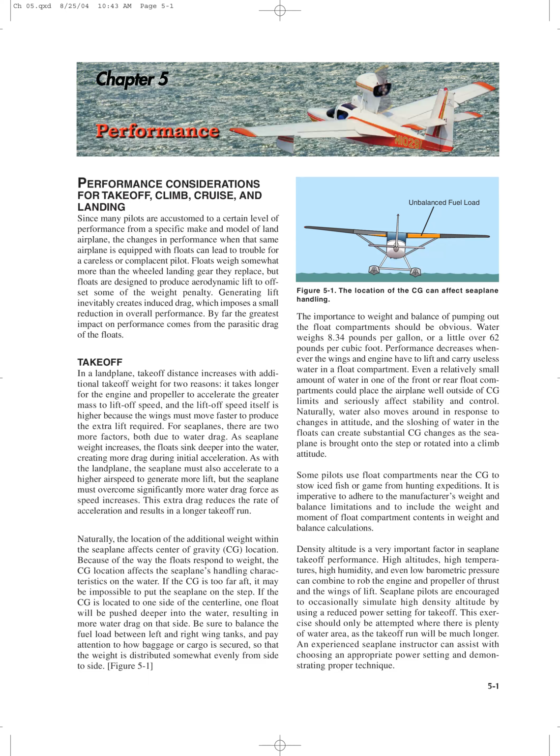Performance considerations for takeoff, climb, cruise, and landing. Since many pilots are accustomed to a certain level of performance from a specific make and model of land airplane, the changes in performance when that same airplane is equipped with floats can lead to trouble for a careless or complacent pilot. Floats weigh somewhat more than the wheeled landing gear they replace, but floats are designed to produce aerodynamic lift to offset some of the weight penalty.